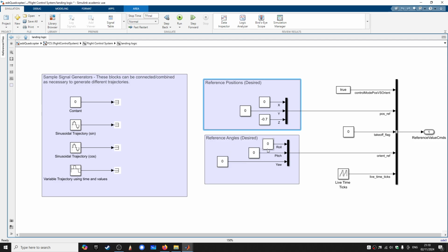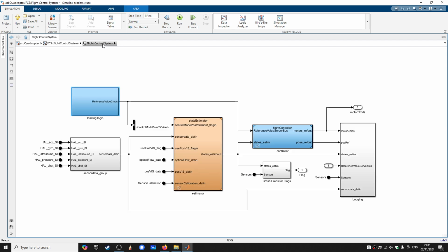We just leave the roll and pitch as they are for now, because we generally want roll and pitch to be 0 unless we are maneuvering somewhere, which in our case will be automatically calculated. I'll go on about how that is done a bit later. So going back, this block handles our desired trajectory.